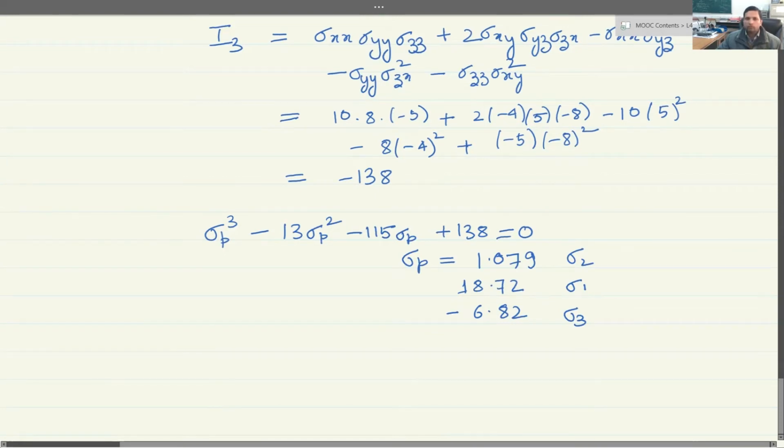What we have found out so far are only the values of sigma 1, sigma 2, sigma 3, meaning let's say there was this orientation and then you rotated it in some other condition. So here, earlier one, you had normal as well as shear stresses acting, but now you have only normal stresses acting. So we have found the values of those sigma 1, sigma 2, sigma 3, but still not given you the equation for finding the theta. We'll come to that.